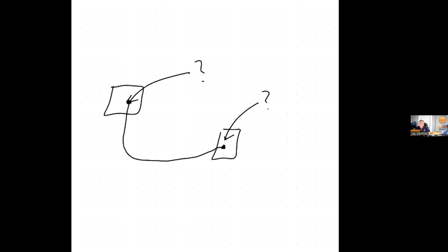Because this box might be switched out in the future, or I might not have that information, we'll always assume the worst case scenario. So we'll always read from that left-hand column. That's just going to make life safe. So you may have to use a little bit bigger wire than you might use otherwise, but again, it's going to protect you.